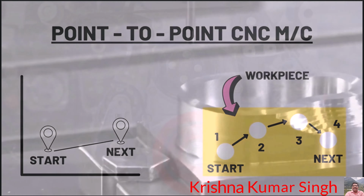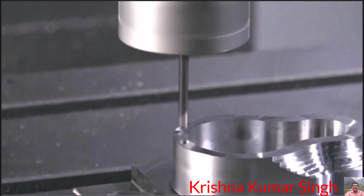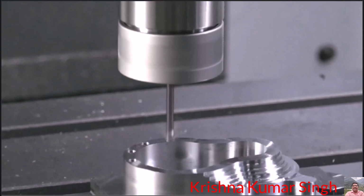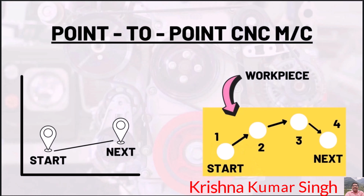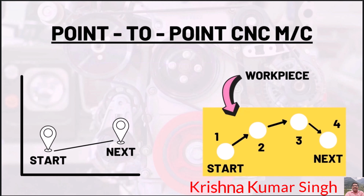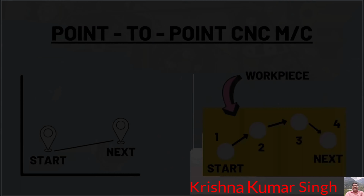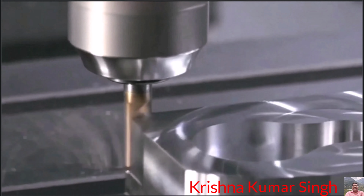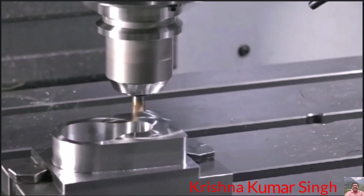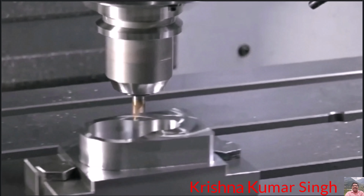The servo system moves the slides to the position and no slide movements occur until the cutter has retracted back. The machines using the system are drilling, boring and tapping machines. In this system, while the cutting operation is in progress, the slides of tool or workpiece move continuously to generate angular surfaces, 2D curves or 3D contours. Milling machines adopt this system pretty well.